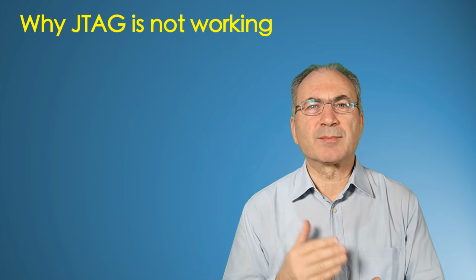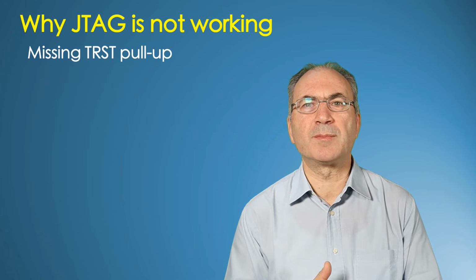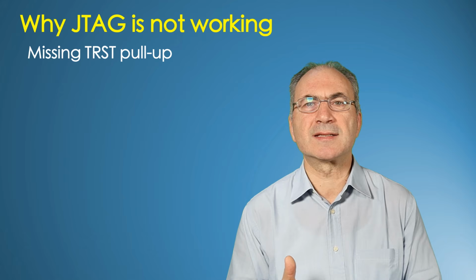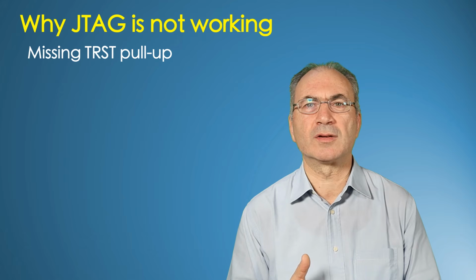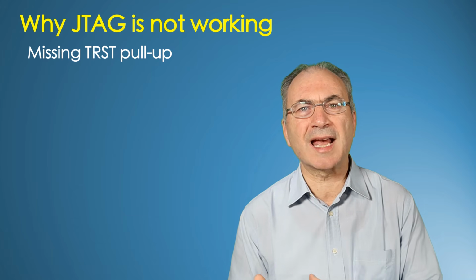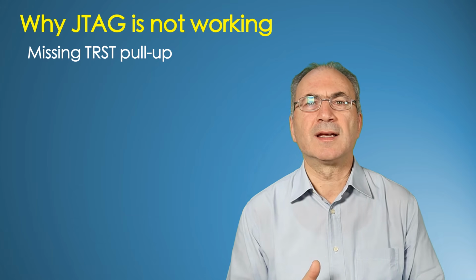Maybe in the mass production it is missing the pull-up resistor on the test reset pin. In this way the JTAG interface is always in a reset state and it will not function. This issue can be solved putting a resistor of about 300 ohm or 1 kilo ohm between this pin and VCC.